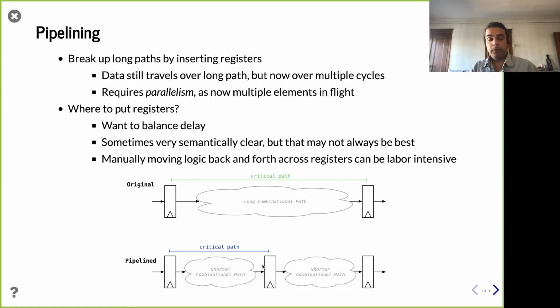And so what's nice about having this, in this case, pipelined? Well, we shorten the critical path so we can increase the clock frequency. Now, if you look at the delay of any operation, let's say an operand came in here and goes through your stuff and comes out over here. The delay for that particular piece of data is going to be the same or longer after you pipelined, right? However, the throughput should be increased, right? And so, wait a minute, I have the same or longer delay, but throughput's increased.